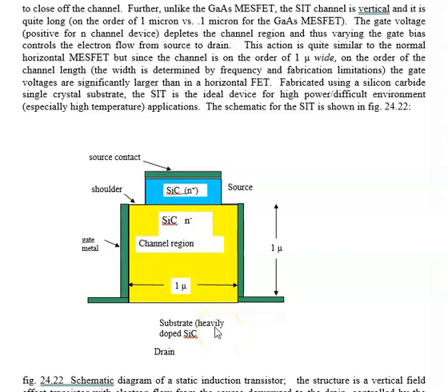The whole thing is made on silicon carbide. Silicon carbide is a very nice material. It has some advantages. It also has some disadvantages. First, the bad news, it cannot be grown in 15-inch boules like silicon. I believe the highest even today is 4 inches. So the number of devices that we can pack onto a wafer is severely limited.